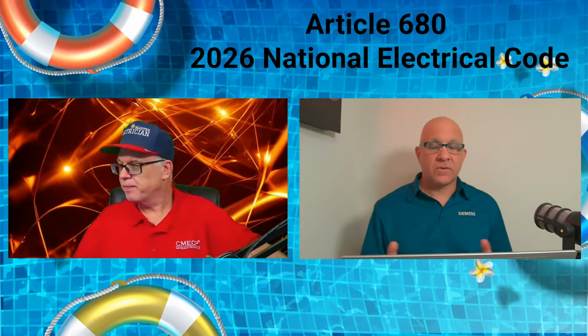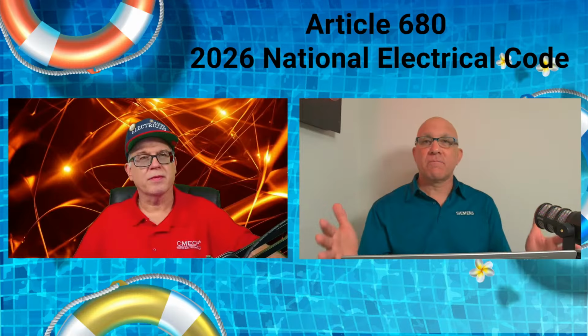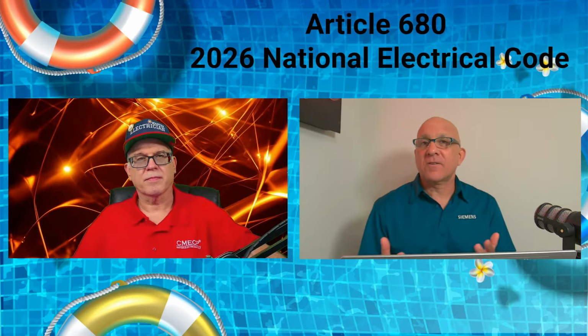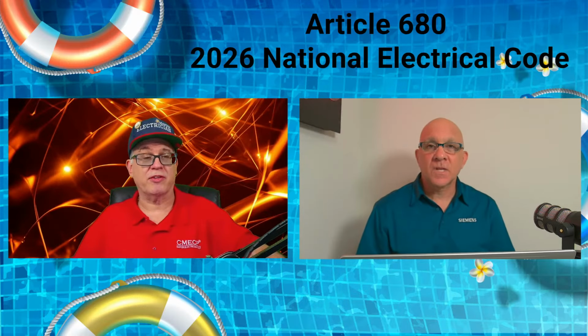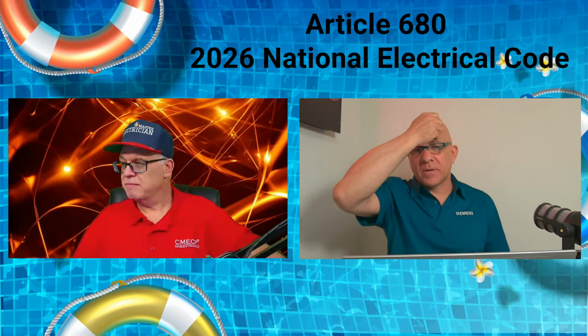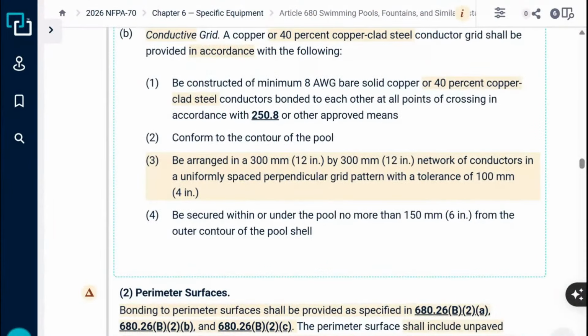I think if you go purchase the copper grid, some folks call it the copper grid mat, copper grid mesh, the code just calls it the copper conductive grid, those manufacturers, I think, are manufacturing 16 by 16, because that maximizes the distance and uses less copper, because the code permits the 4 inch tolerance. Somebody could fact check us on that though. Pull up a manufacturer who makes this stuff and double check the size. And many of the people out there probably have never been involved in using conductive grid like this.